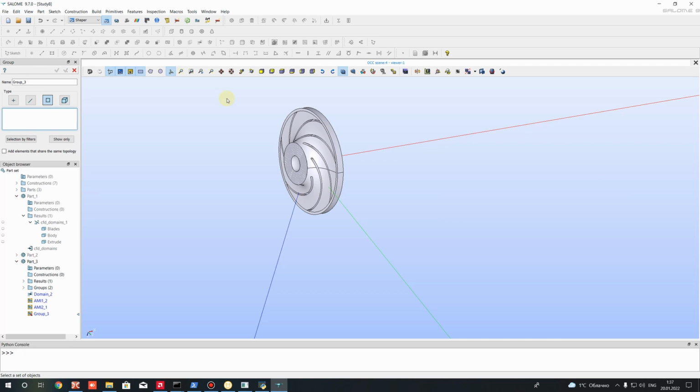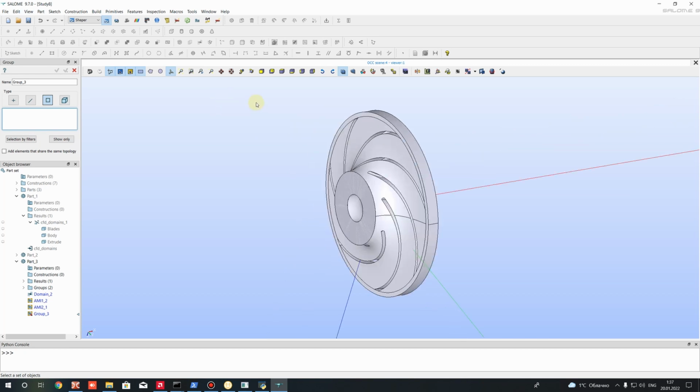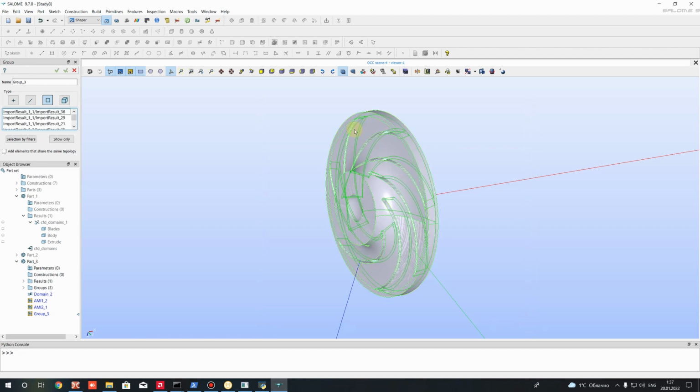After that, we have to create surfaces of our wall. All surfaces. We just press the left mouse button and create the box. Choose all faces, and here we have to delete these two faces for EMI1 and EMI2. Let's try to find it in our tree.